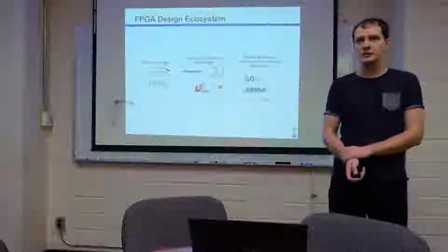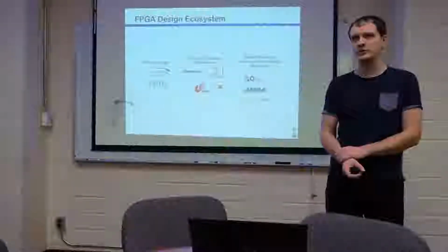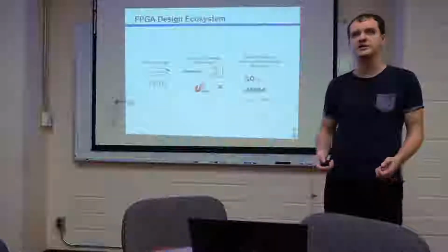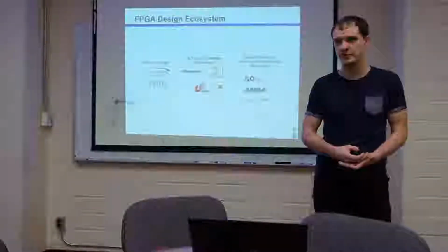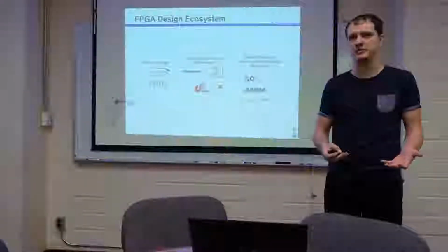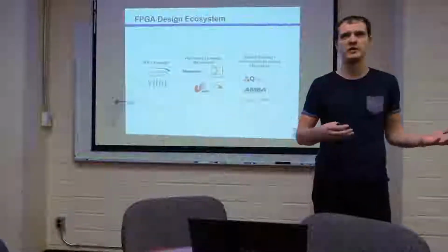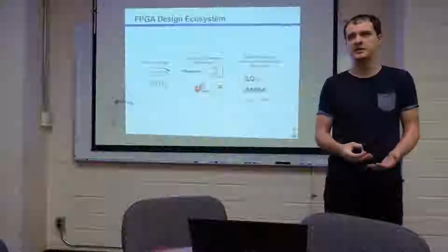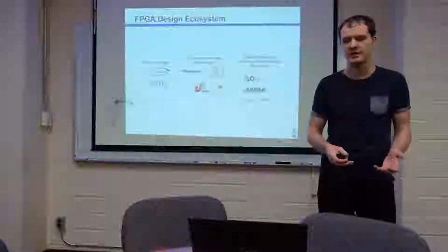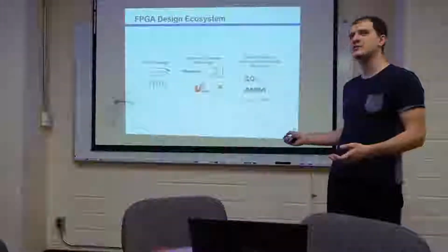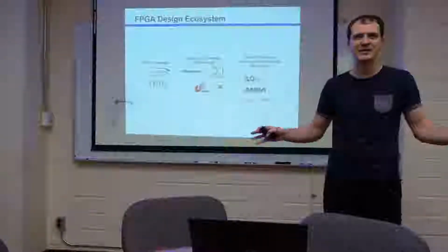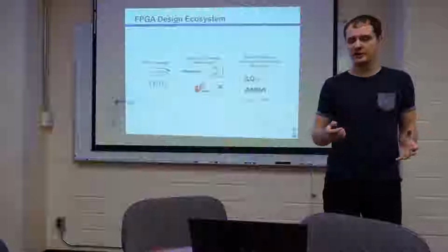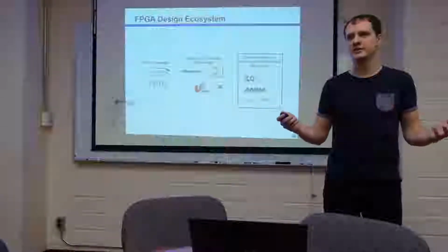And there's another class of tools that maintains the structural spirit of hardware design, and these are the system building / interconnect synthesis tools. And every vendor kind of has one. Altera / Intel has QSYS, now called the Platform Designer. Xilinx has part of Vivado that does that, and I think Lattice, the other guys, have their own thing. I don't know what's going on there, but I know they have something too. So my tool that I'll be talking about lies within this space.